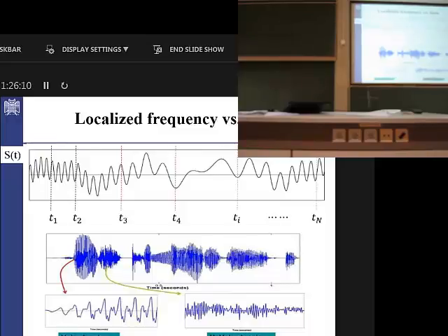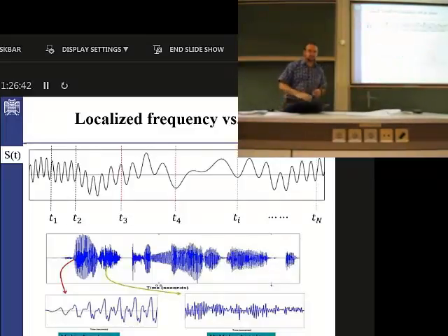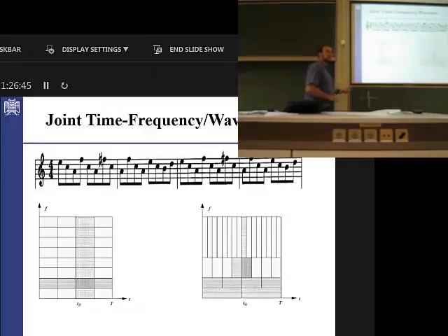In most cases, unvoiced phonemes are called pseudo-noise, because they are like noise. And if you take the spectrum of that part of the speech signal, it fully fills out the entire spectrum from the lower frequencies to higher frequencies, like noise. But for the voiced case, it's not like that. Just certain frequencies are activated, and they are normally harmonics. So these are some examples where we localized the frequency pattern within the time domain.